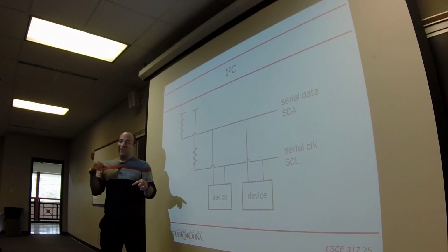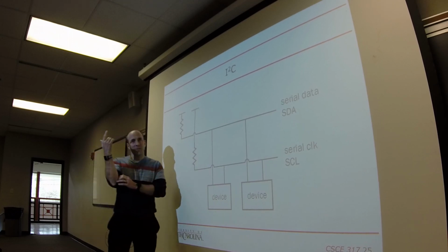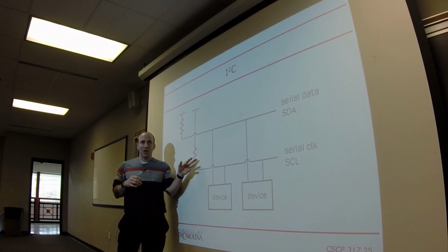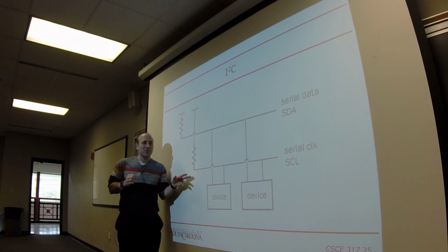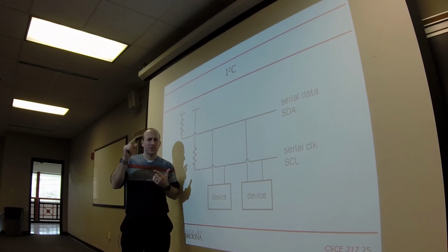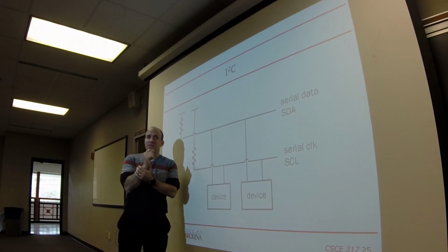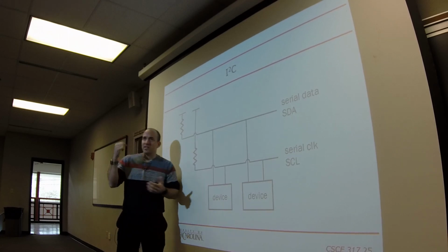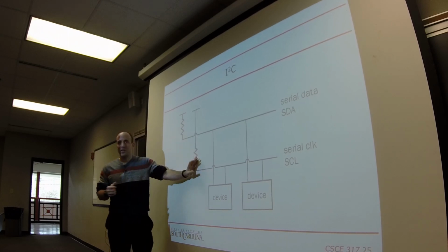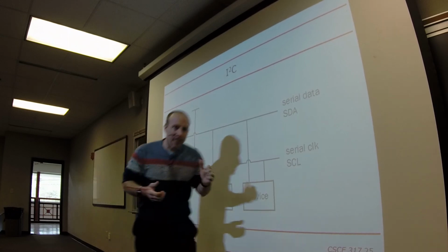Well, I think if you look at the DDR register, there's an option to turn on a pull-up resistor. No, well, that would have saved some trouble. So I think you can turn it on if you set up the control, the DDR and port, right? If something is an input, you set the DDR to 0, but then you can set the port for that input to 1 or 0, which defines whether or not it has the internal pull-up activated. But anyway, that's basically the idea.